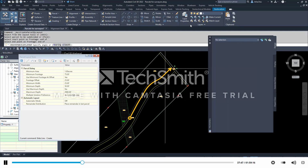Are we going to go 90 degrees off this line? Or are we going to go 85, 45? What are we going to do? If I just hit enter, it's going to go 90, so I think we'll just choose 90. And now I remember, I started it from here, so it's going to go 1 acre, 1 acre, 1 acre, whatever's left. If I started down this way and went that way, 1 acre, 1 acre, 1 acre, whatever's left. Okay, so enter. That's not bad.